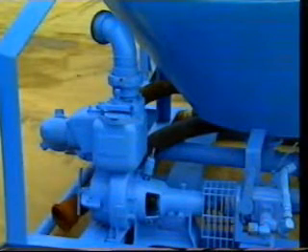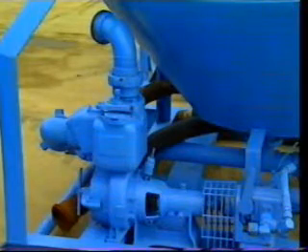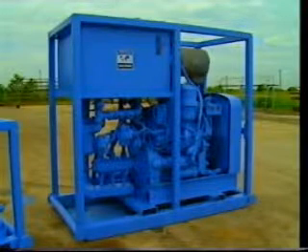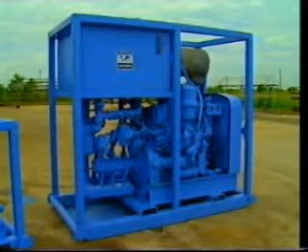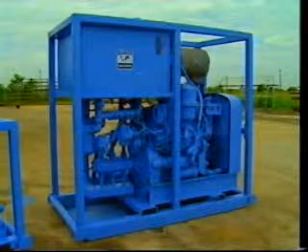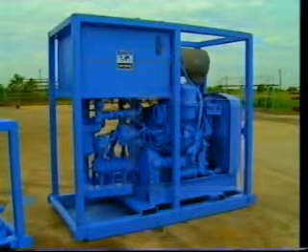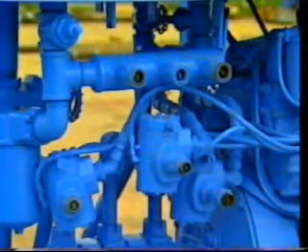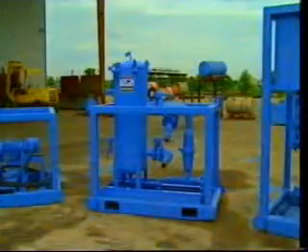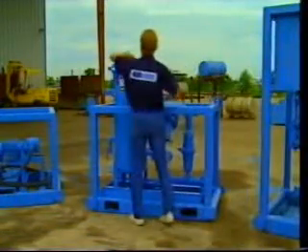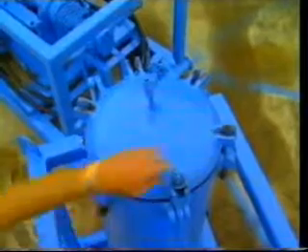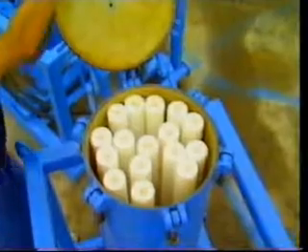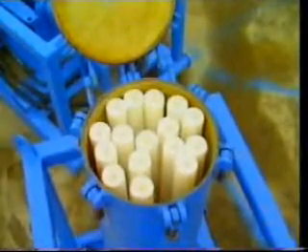Centrifugal pumps transfer the fluid at low pressures into the blenders and displacement tanks. The power pack provides the necessary hydraulic horsepower to operate the centrifugal pumps. The prime mover is usually a diesel motor and, in conjunction with a hydraulic pump, provides an independent variable control for each hydraulic motor. Filtration of the treating fluids is a critical concern when gravel packing. Any fluids used for gravel packing should be filtered, first when stored and again after mixing the gel.